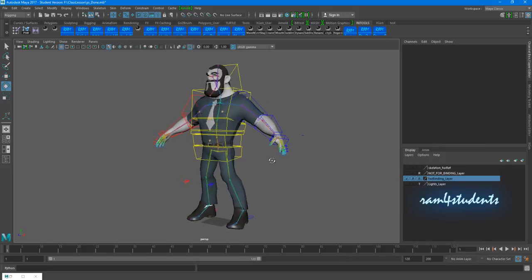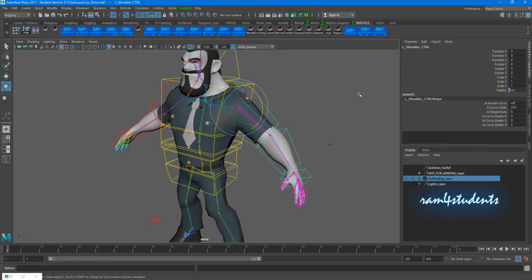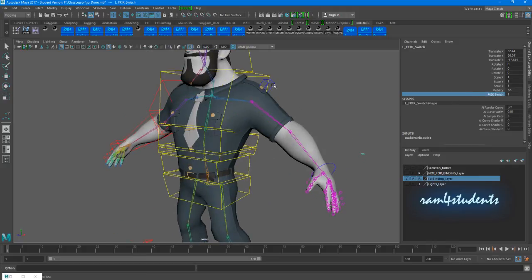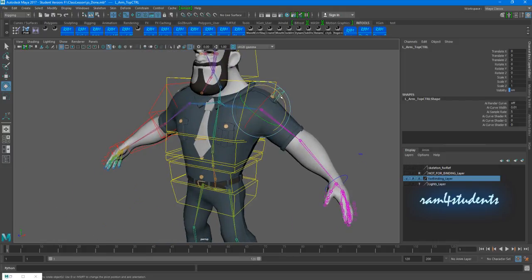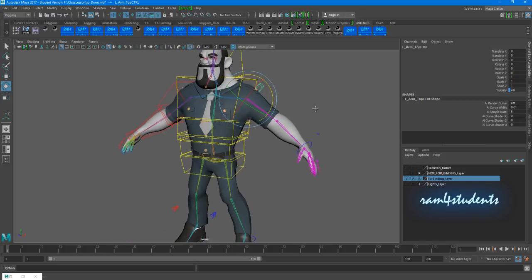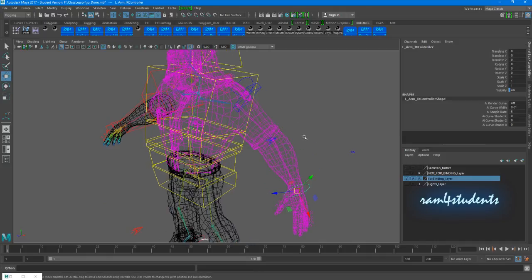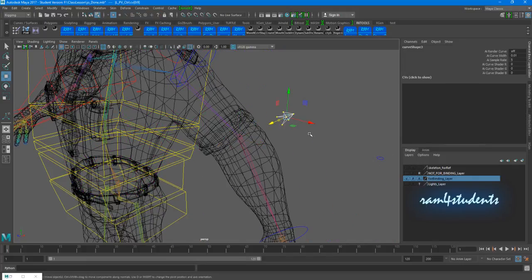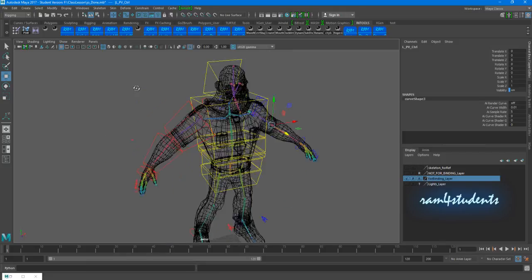Hi guys, welcome back. If you check it out, I edited all the curves using components, and if you check this one also, for IK this root I just created a small simple thing because I'm not going to move it or rotate it. I just need it so that I can link it with this clavicle controller. But right now this is working. You got a pole vector here, so right now I can select this curve, F8, I'll move it back a little bit, that's fine. The same thing you can do on the other side.